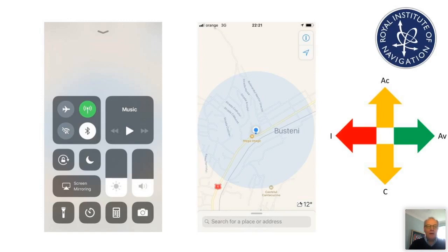Well, here I'm at about a few hundred meters of accuracy, typically 200 to 500 meters. And that's because my phone is giving me a position based on cellular. So this is just base station positioning based on a raw sort of power level from the base station. Again, this will get better with 5G.